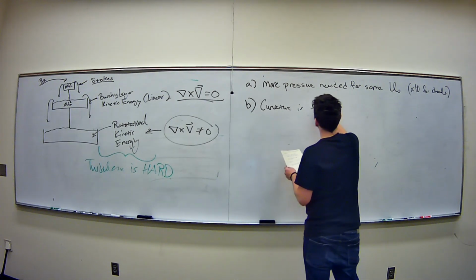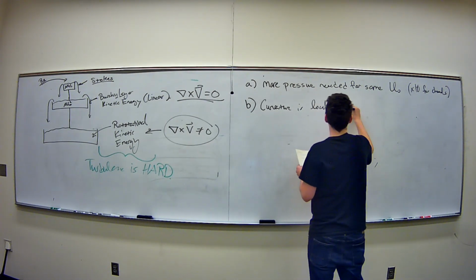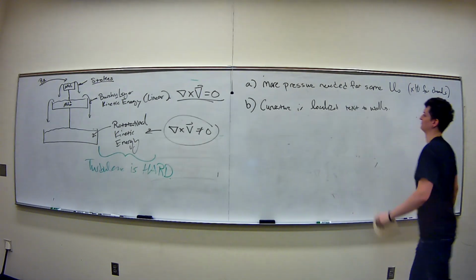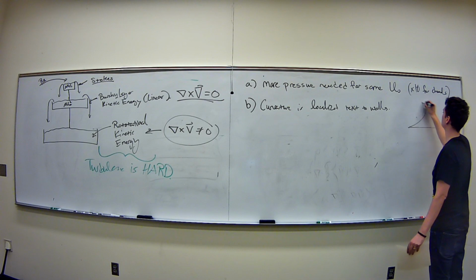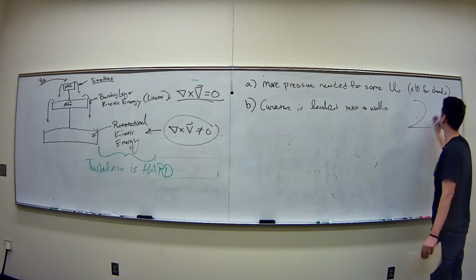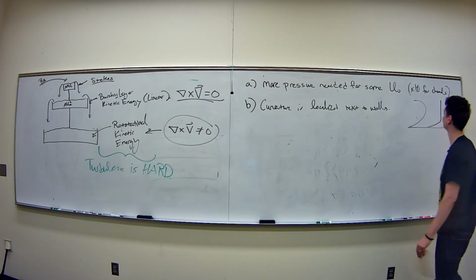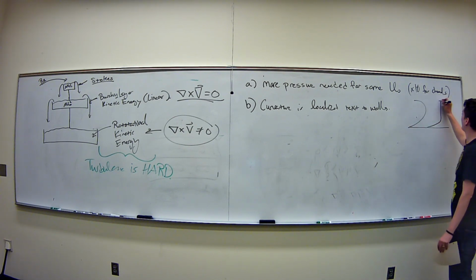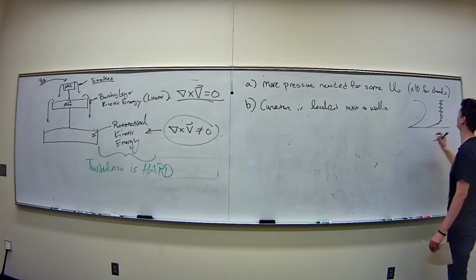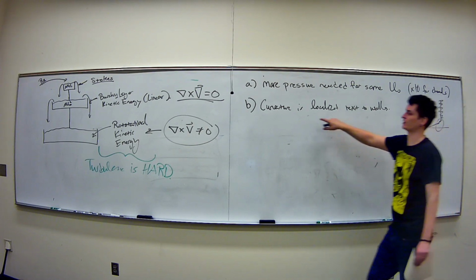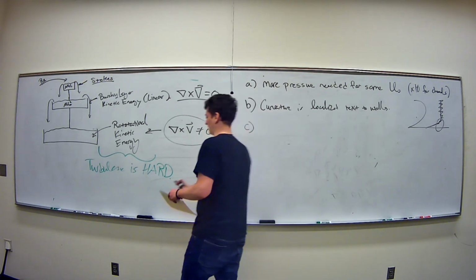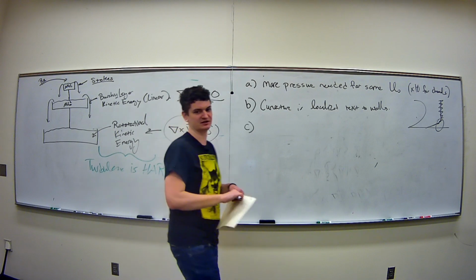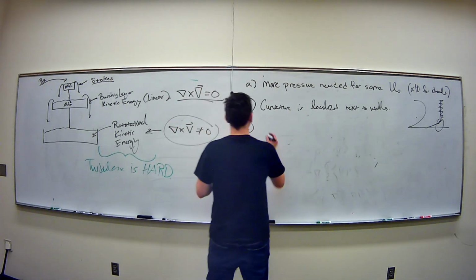One other thing is that the curvature in turbulent flow is localized to walls. That's the idea that in laminar flow the profile looks like a quadratic, and then for turbulent flow it looks like this, in a logarithmic sense. So it almost looks flat, but there's this region of fluctuation, so all the curvature is really confined to being close to walls. And that comes from even a general sense of the equations that we derive. You can show that.